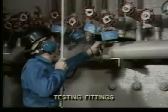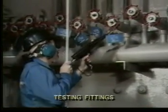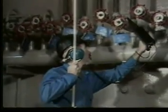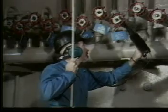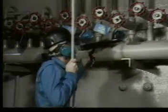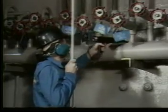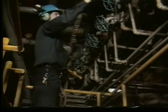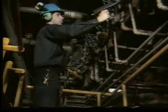To test fittings such as valves, piping, and flanges, scan for a rushing sound or white noise. Use the scanning mode of the Ultraprobe as shown earlier. Adjust the sensitivity to move from gross to fine sounds, and move back and forth to confirm the leak site.